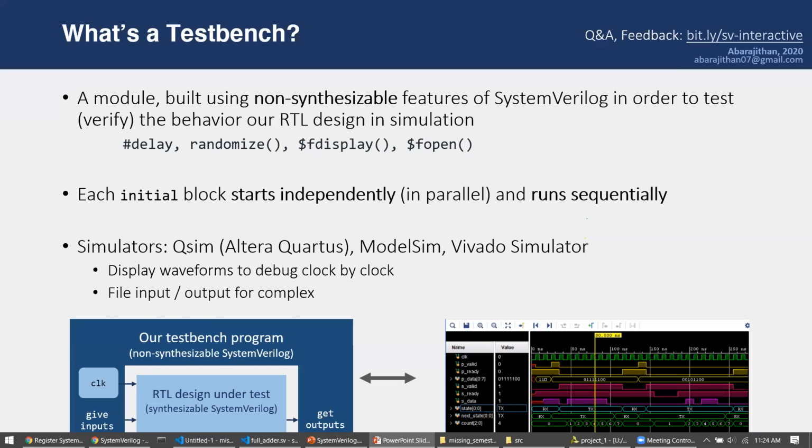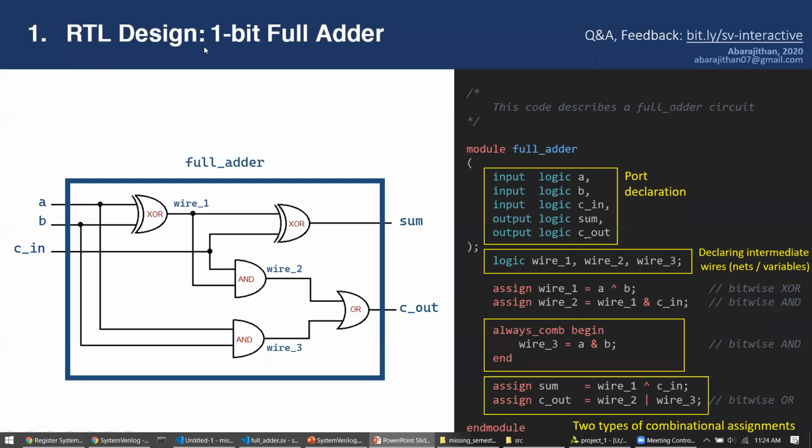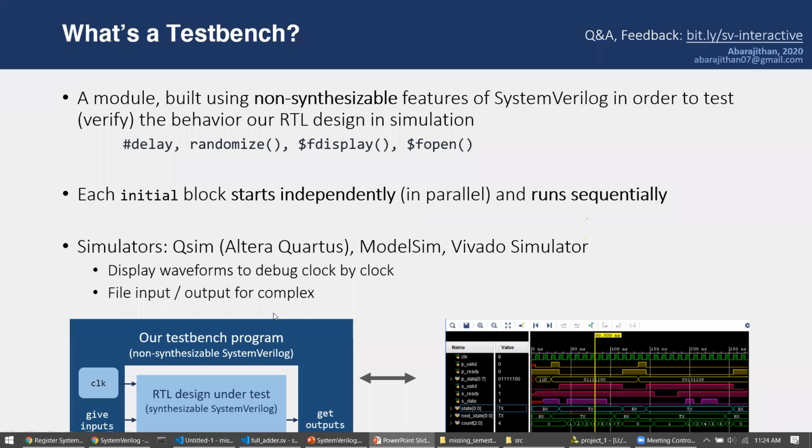Before that, what we did here is the RTL design. That is, we have described the circuit. Next, we are going to do a test bench. So what is a test bench? It is non-synthesizable, so you can't put that in a chip. But we will be using it to create a module using which we will be verifying the behavior of the RTL.